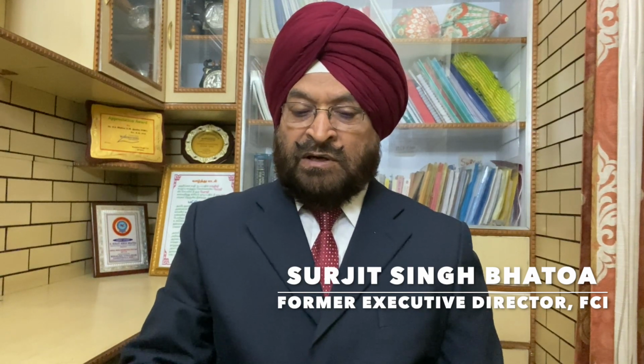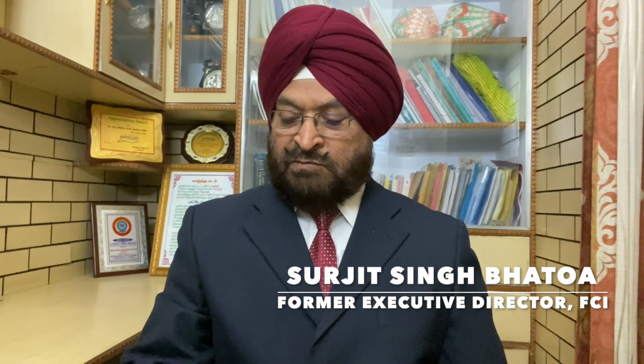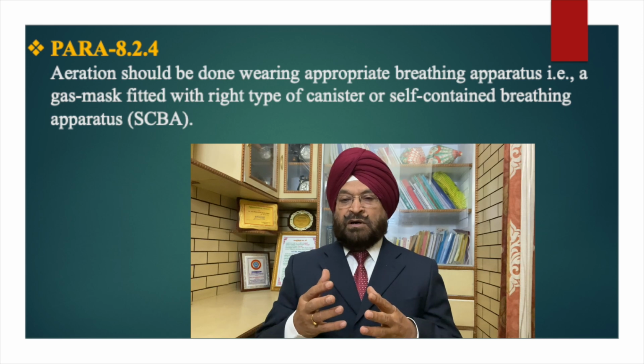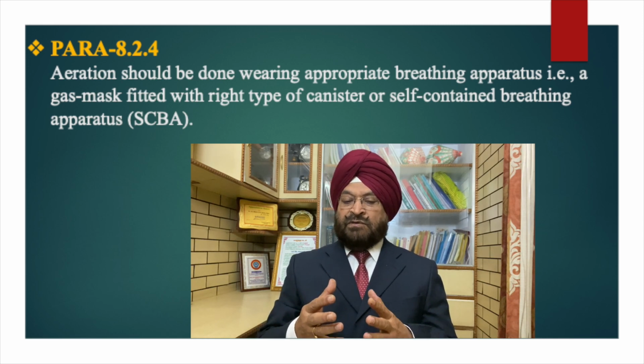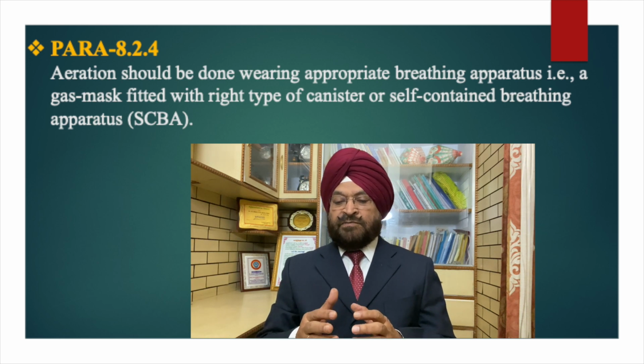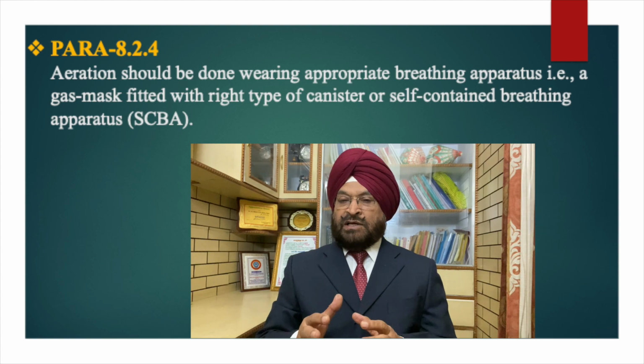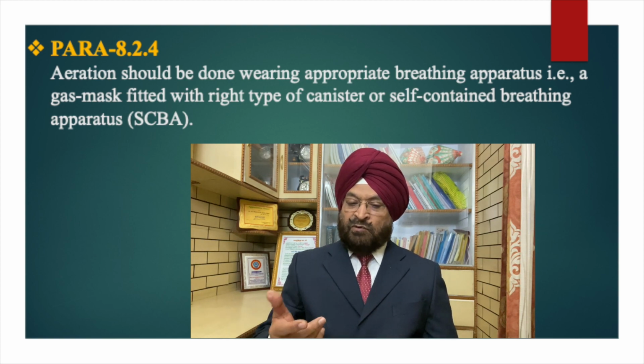Right? That's why a limit of 0.3 ppm has been prescribed. Further, the aeration should be done wearing appropriate breathing apparatus. Right? That is, a gas mask fitted with the right type of canister or a self-contained breathing apparatus, at the time when you are removing the cover.